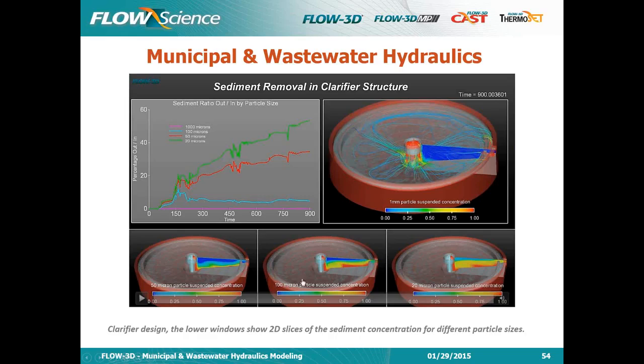At coarser particles, 100 microns, these are inverted actually. This is the 100 and this is the 50 and this is the 20. So at 20 microns we see that most of the stuff is being entrained and goes straight to the output. And not surprisingly, this is kind of 1 minus the removal percentage. So for the very coarse particles, if you look at the outlet, nothing's making it to the outlet. It's removing all of the coarse particles, and about 90% of the 100 micron particles.